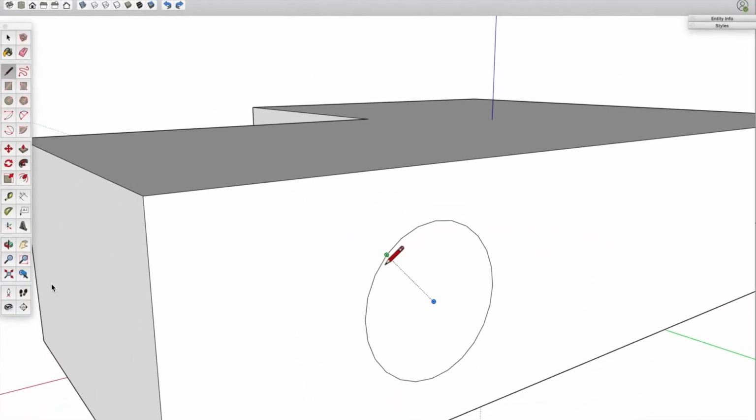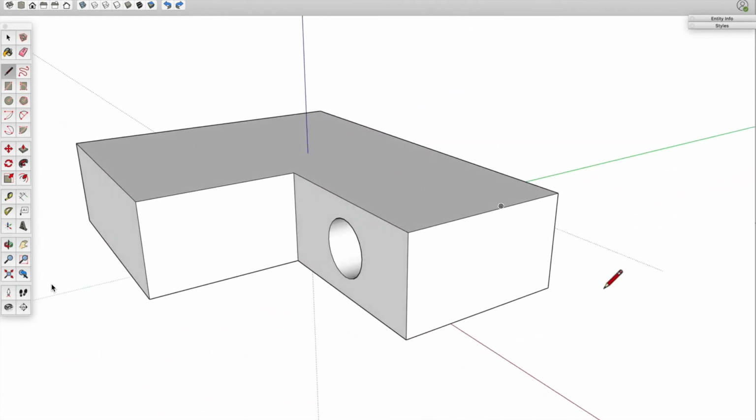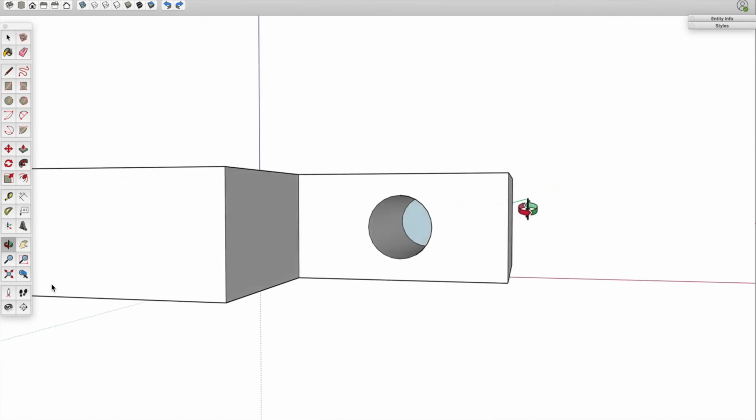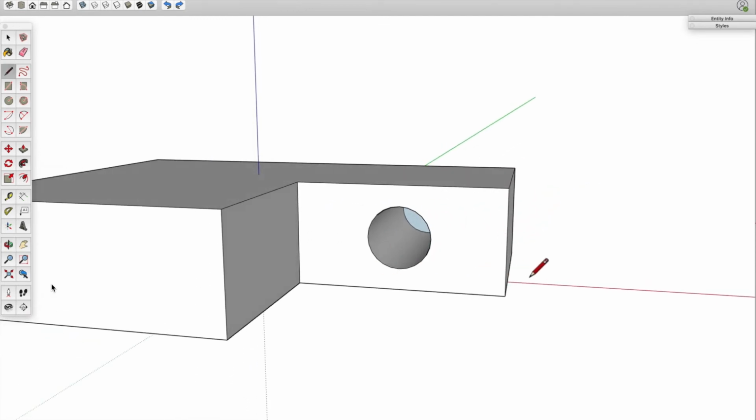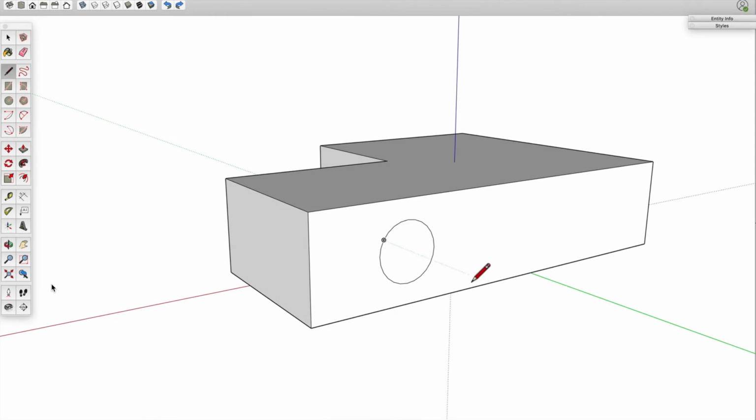And you trace from endpoint to endpoint, which causes SketchUp to say, got it, you need to heal that surface back in. Roll your mouse wheel backward, orbit around, and you'll notice that this side is open and you have a tunnel going here. And if you come around the back side, this side is closed off, just as we wanted.